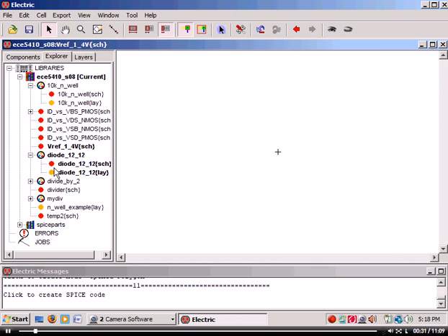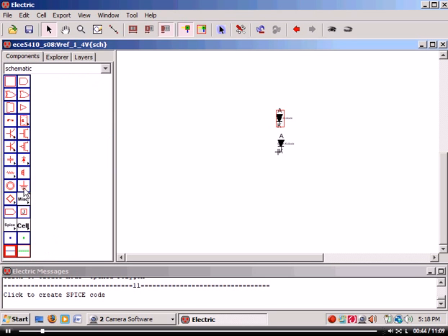I'm going to drag my symbol over, show it, Control copy, Control V, drop it over here. Now I'm going to come down. Now I can put my ground in, but if I use ground symbols, I know when I do my LVS, I get what? It's going to say ground implied. Okay, so I'm going to go ahead and do the off page and put one there, there, and there, and hit fit.